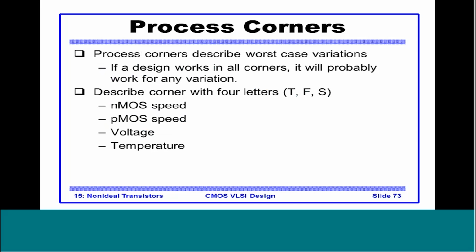Let's say we manufacture a chip and give it to a customer. We have to tell him the temperature range in which he can operate this chip. What if the chip is meant for space applications? The temperatures can go below 0. What if they are used in devices that are switched on all the time, let's say a mobile phone? The temperatures can go quite high. So we have to define a temperature range for a particular chip, and we will define a voltage for a particular chip. These two are the specifications.